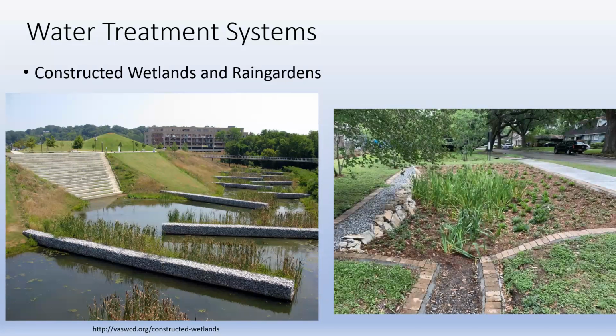On a smaller scale, rain gardens function in similar ways. Rain gardens, particularly in areas where you're going to get a lot of rain, such as Louisiana, are a great way for addressing some of that excess stormwater, really trapping some of those sediments, trapping some of those fertilizers, contaminants, and making it aesthetically nice. So you can get these kind of features implemented in landscapes or in certain sites, depending on what it is.